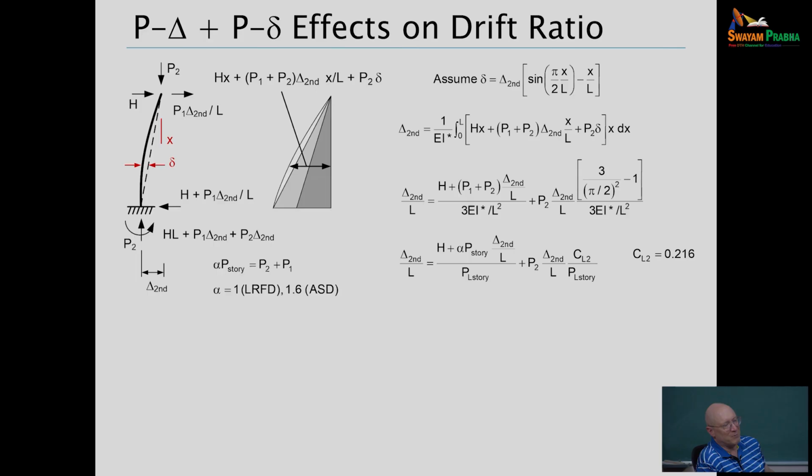So here we're going to invoke some approximations. If we're right at buckling in this system, then the equation at the top of the screen is basically the delta you would have. That would be the form if it's buckling. If it's very small P2, it would be a cubic equation, right? So this is just to be able to work the approximation here. We need some form for a curve to approximate a delta.